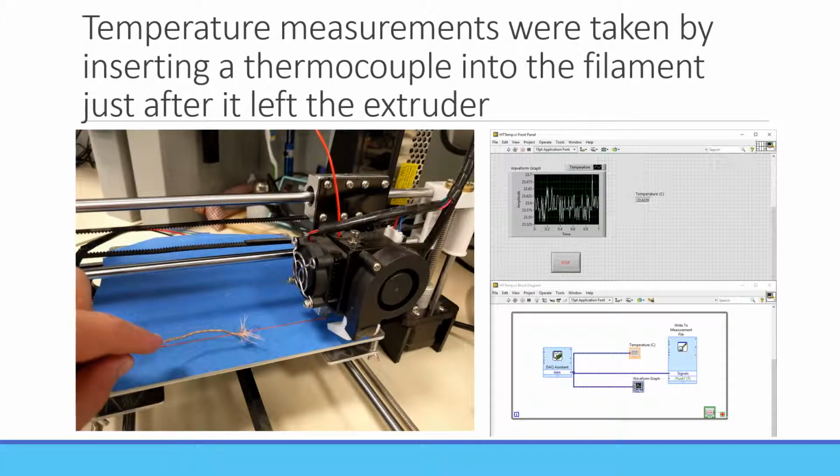In order to measure the cooling rates as the 3D printer deposited the filament, I set up a LabVIEW VI to measure temperature over time and plot it to an Excel file. I then set up the 3D printer to print a straight line from left to right. As the printer would print, I would insert a thermocouple just behind the extruder to take as high a measurement as possible for temperature to start out. The hope behind this was that it would give me a wide range of temperatures over time to do data analysis on to see how fast the filament was really cooling.